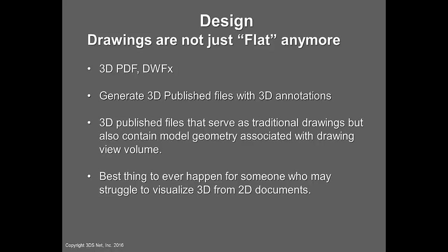I'd like to point out that looking at that 3D, we're saying drawings are not flat anymore. We can make 3D PDFs, DWFXs. We can publish these 3D files with the annotations. You can cut a view that looks just like a traditional view, a plan view of an area, but all the labels are actually in 3D space, and you publish the 3D geometry for that drawing view.